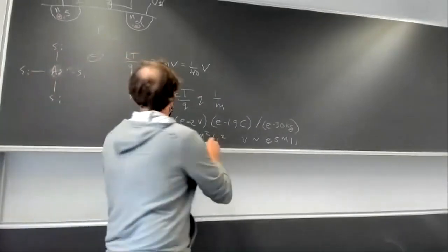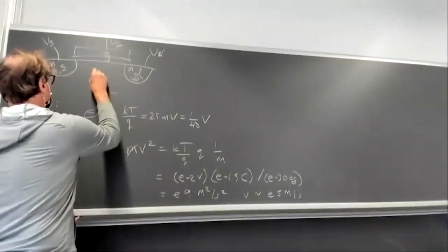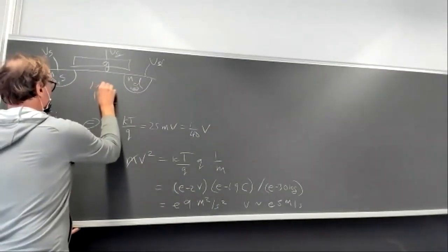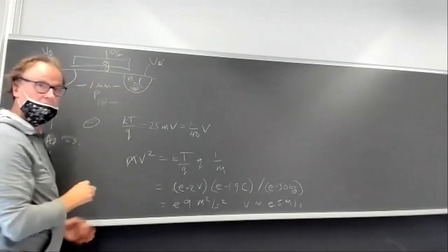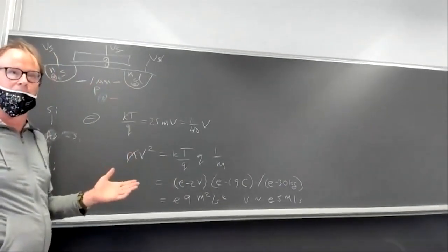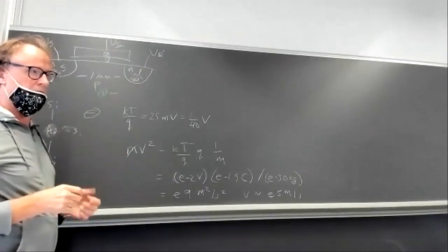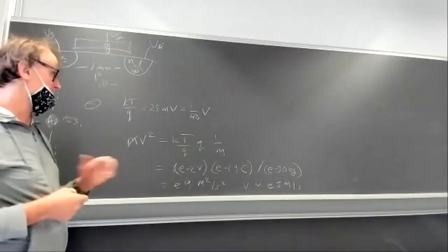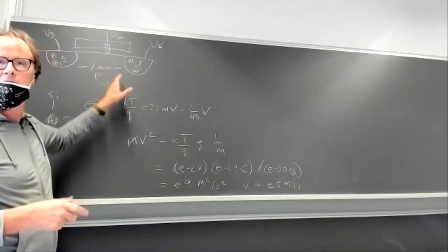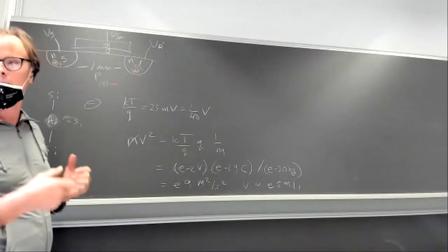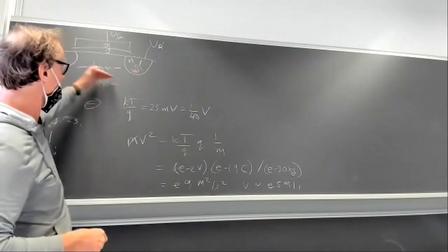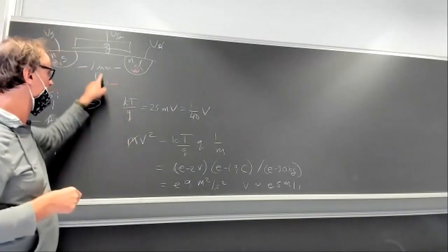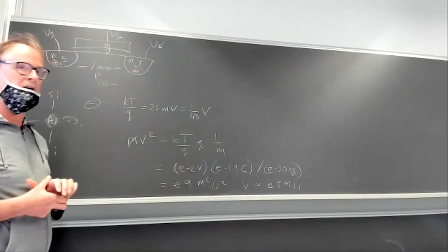And let's calculate if we have a transistor here. Let's just do it in round numbers again. It's 1 micron long. That's actually a really long transistor nowadays, right? With the latest logic families having channel lengths of 10 nanometers or something, 100 times smaller than this. This is the kind of transistor you build for analog, like a micron long. So how long would it take a freely moving electron to cross this if it's moving at 10 to the 5 meters per second?